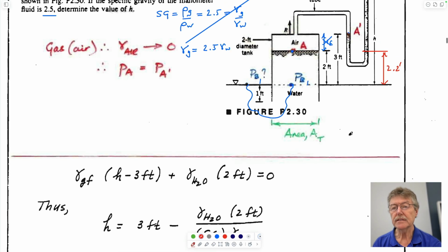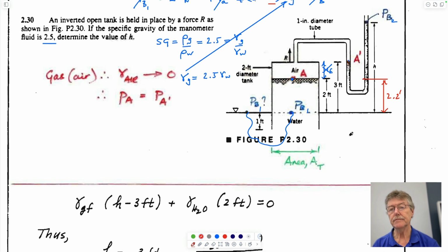And that makes sense. And so in other words, what we're doing is we're calculating the actual height of this. So what it's done is the vacuum in here, or the less than atmospheric pressure, has sucked this up. So there's a vacuum in here. The magnitude of that vacuum is actually 0.8 feet. It's not a full vacuum, but it's 0.8 feet of gauge fluid below atmospheric pressure. Okay?